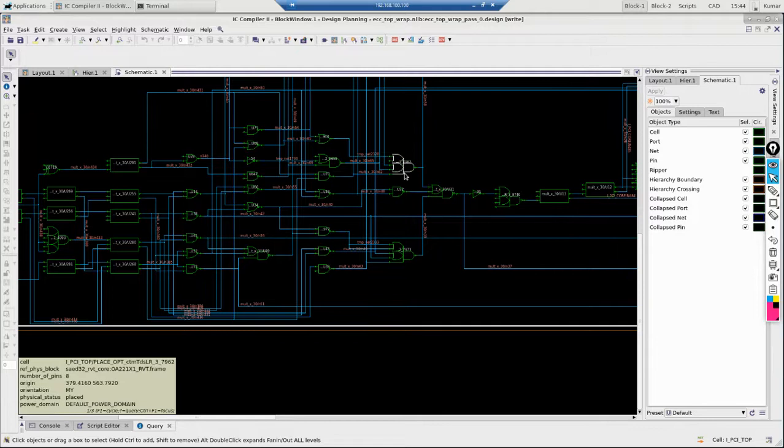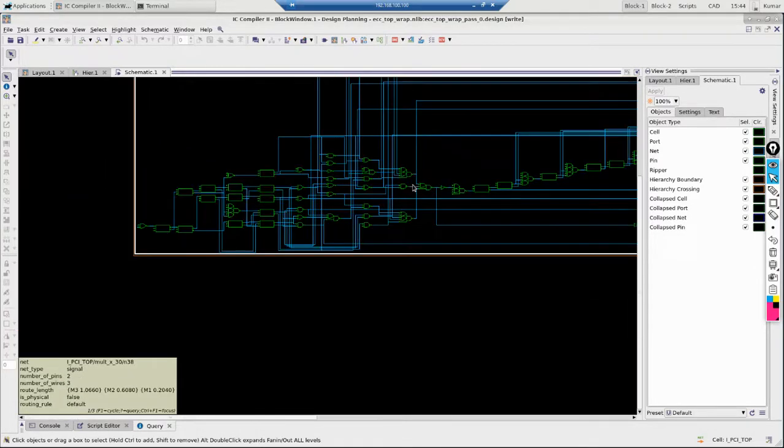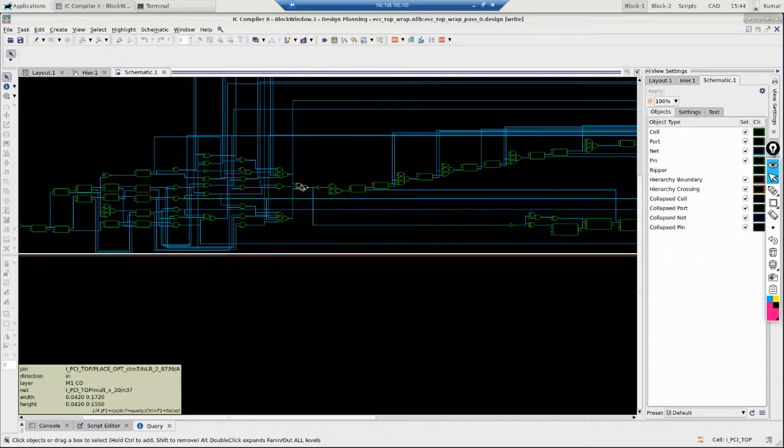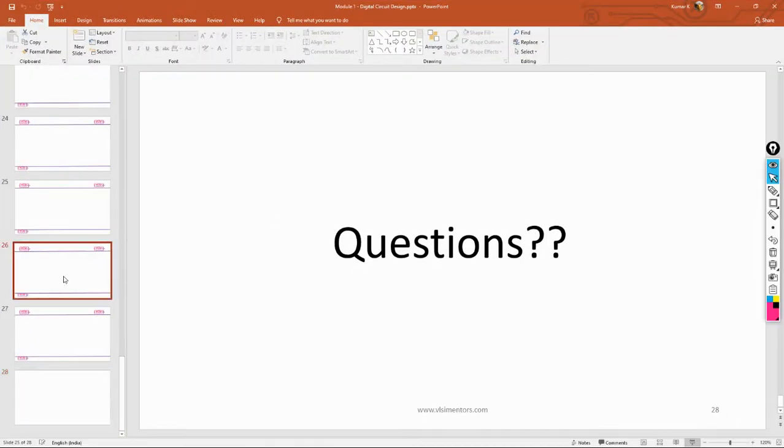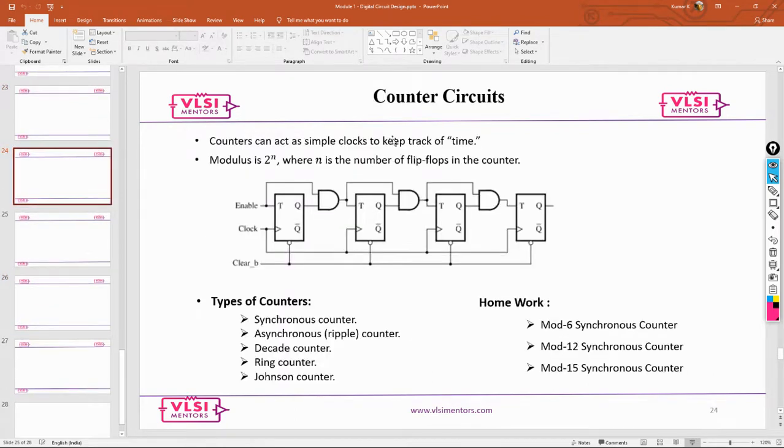So if you look, your design would be something like this. You'll have a lot of paths, probably combinational circuits. Whatever we draw while learning, say for example this counter, how many cells does it have? Only one between the two flops. But in industry, you will have at least a minimum of say 10, or it can be anything. I have seen 30 plus cells. On average there would be 30 plus cells. Don't think it's just one or two. There would be 30 plus cells in the designs that you will see in the industry.